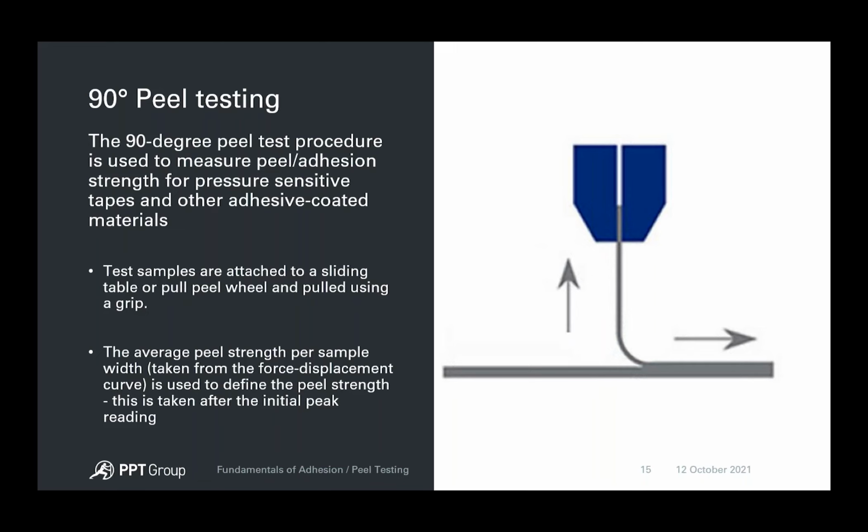Generally, sample requirements consist of a set of 5 specimens that are 20 millimeters wide by 200 millimeters long, or quite honestly, whatever standard that you are testing to, whether it's industry standard or in-house standard. These can be directly cut from the product or prepared under laboratory conditions.